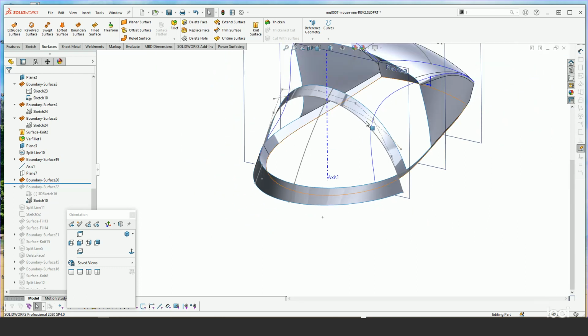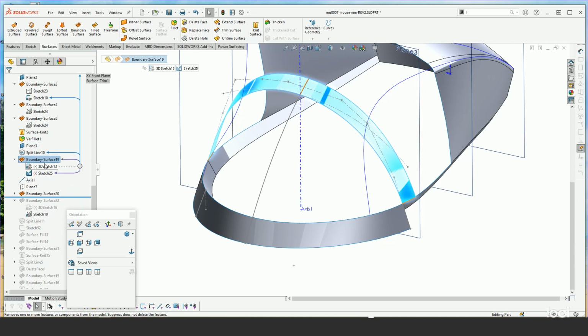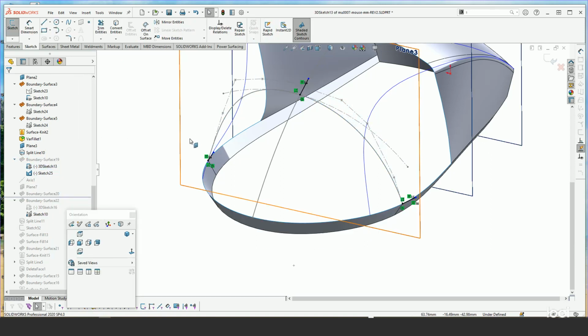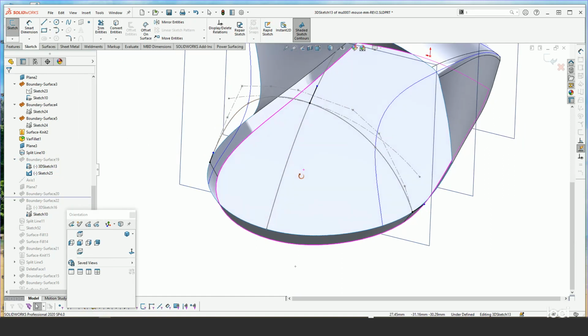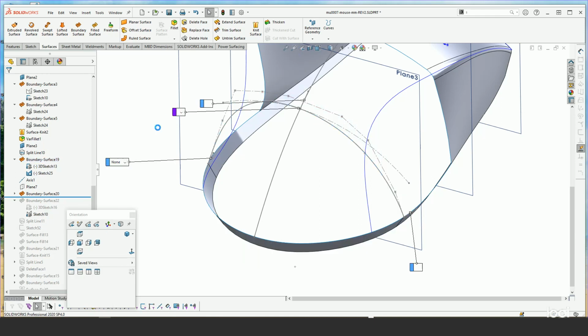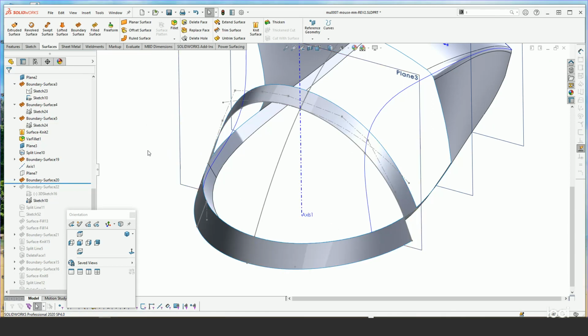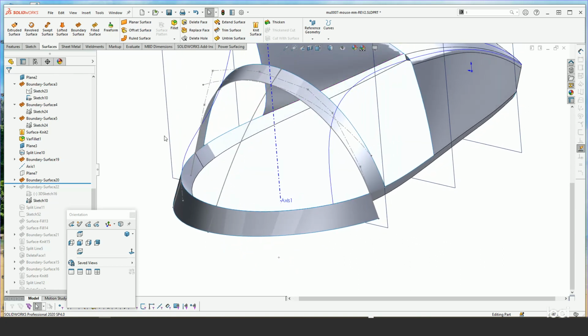And then my first one here, which is 19, goes along the top. And it's very much the same as what I just said with my other reference surface. I have basically three 3D sketch entities here, here, and here, and constraining them to current sketch geometry. And then I create my ribbon surface using those along with the existing edge in my second direction. Okay, so with those I have everything I need to be able to create my fill surface.